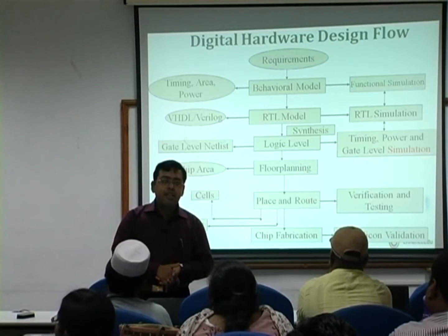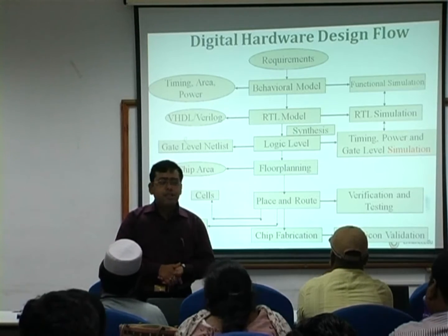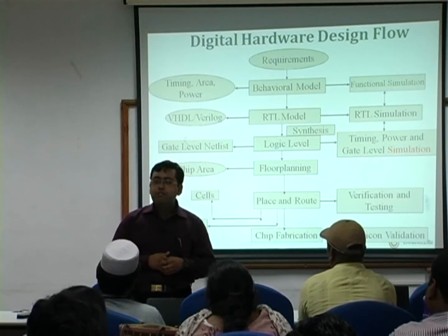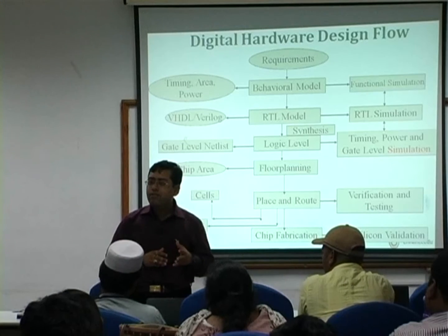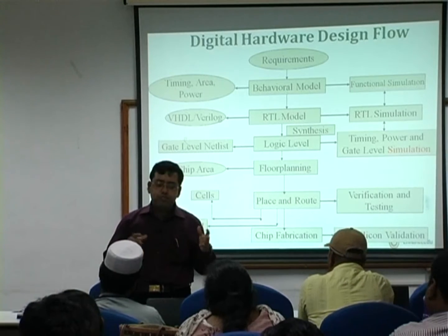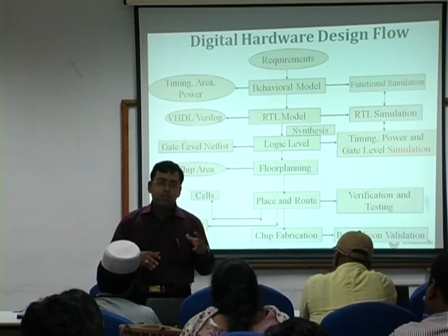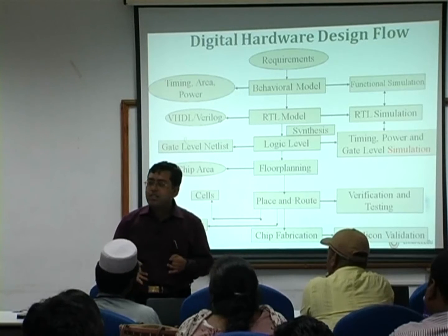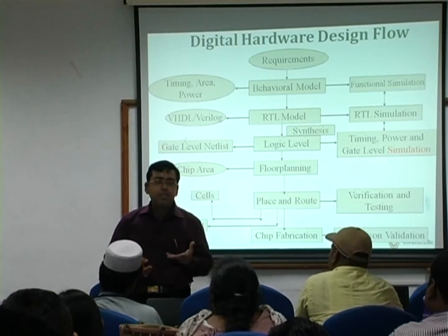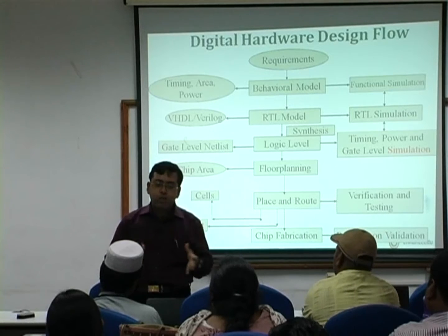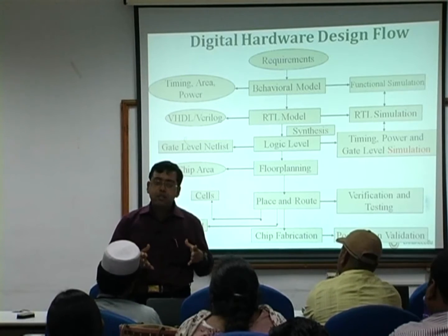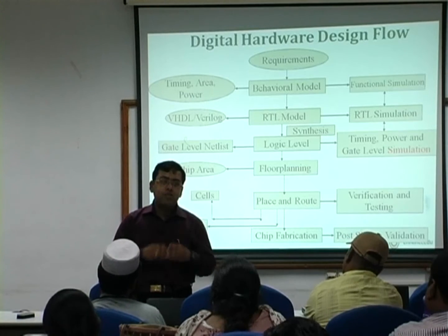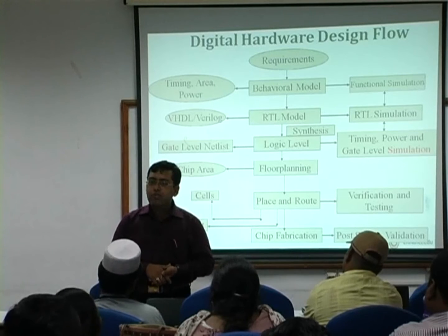So this is again a very important aspect, that is to carve out a testing algorithm that is exhaustive enough to test the circuit, test all its critical paths and subcritical paths and so on, and at the same time the testing set is small enough so that with that small set of test cases you can test exhaustively the entire behavior of your circuit.